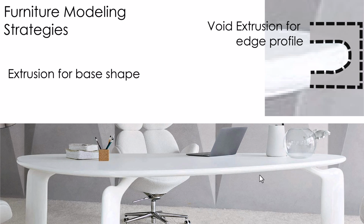Perhaps a simpler example is just a tabletop. If you want, say, a kidney-shaped tabletop, you can draw that as an extrusion. Just pull it right up an inch or two, and then round the edge by drawing a profile that's a void. It's a swept blend, actually, not a void extrusion. And that sweep will follow the path of your kidney-shaped tabletop, eating away at the edge and making it have a rounded edge or whatever edge you want, an OG or that sort of thing.